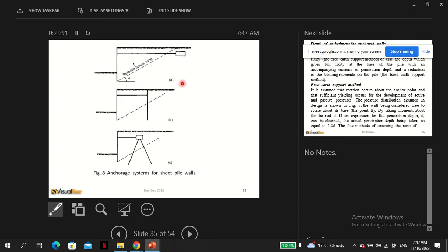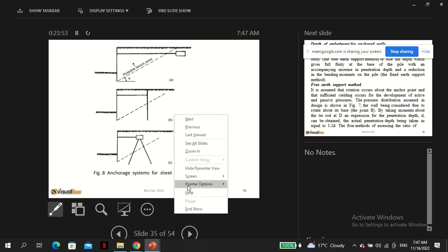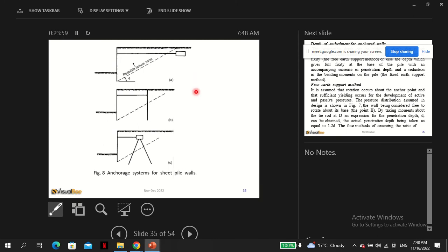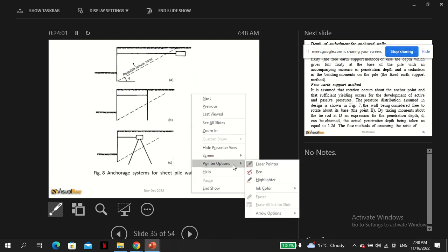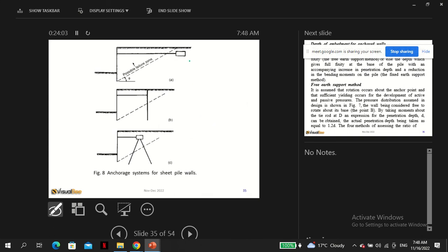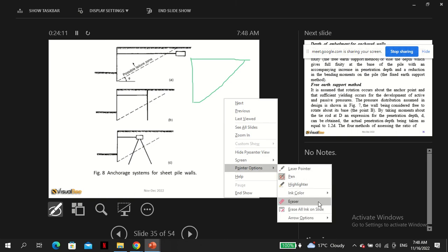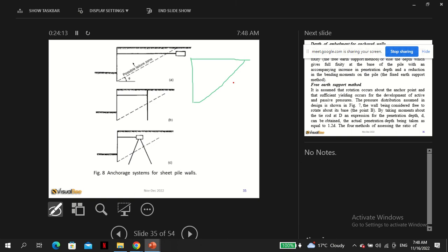So you remember the idea of the geotextile design as well. We said this is your wall, this is the potential failure zone. So the geotextiles have to be designed such that the length is outside the potential failure zone.